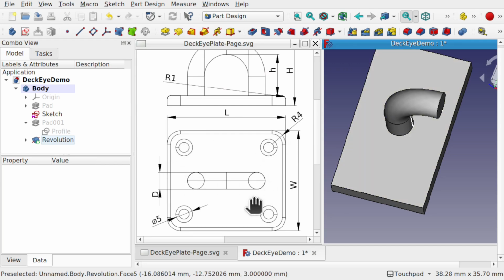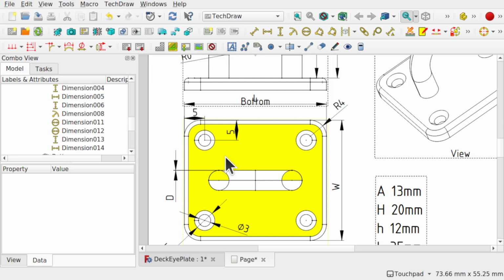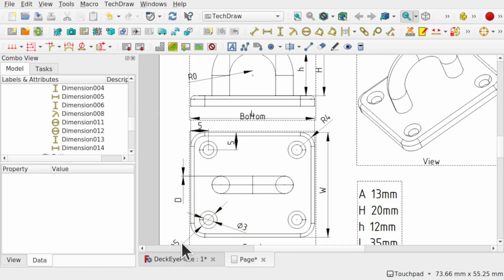So these holes here. Now I have realized that I've missed out some of the dimensions on this plan. So I will update those plans and you'll get something like this with those dimensions in there. And you can see I've created this in Tech Draw, and I'll export this out so the material you'll have will have those dimensions on. So this hole is 5mm away from this edge, and also the inner diameter is 3mm, and we've got the chamfer that brings it up to 5mm there. So 1mm chamfer will bring that up to 5mm.